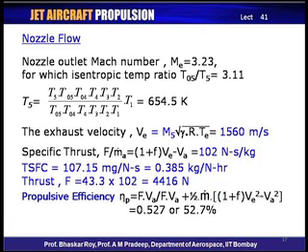So, the propulsive efficiency of a scramjet is not much larger than that of a typical ramjet engine, it is of the same order. So, the specific thrust that we see here is somewhat of a lower order, and what we can do now is compare all the engines that we have computed, all the parameters, and see what values we can get on a comparative basis.